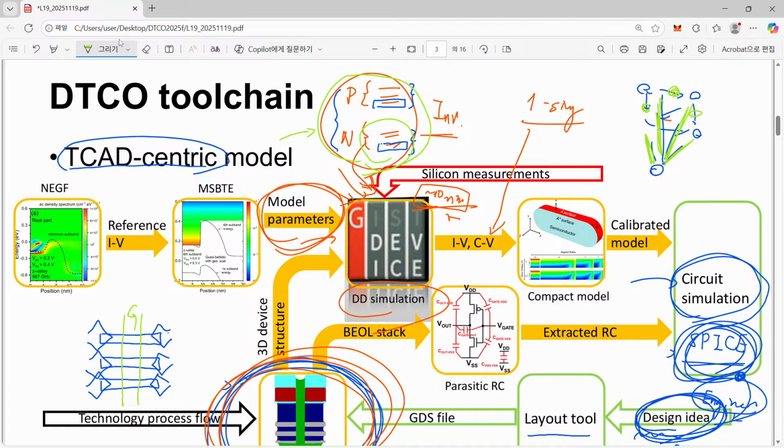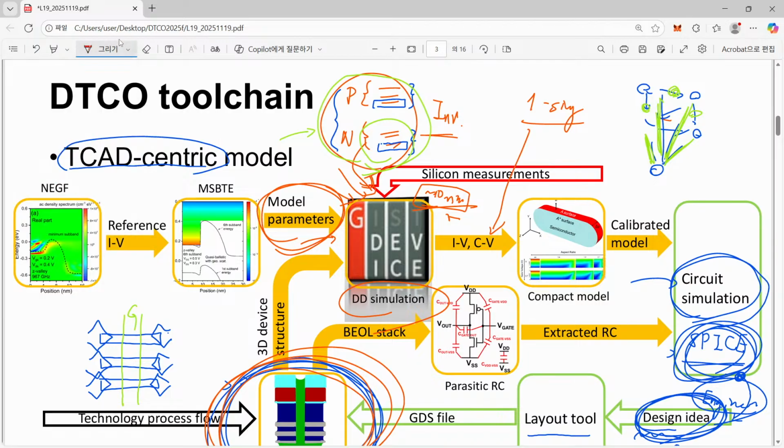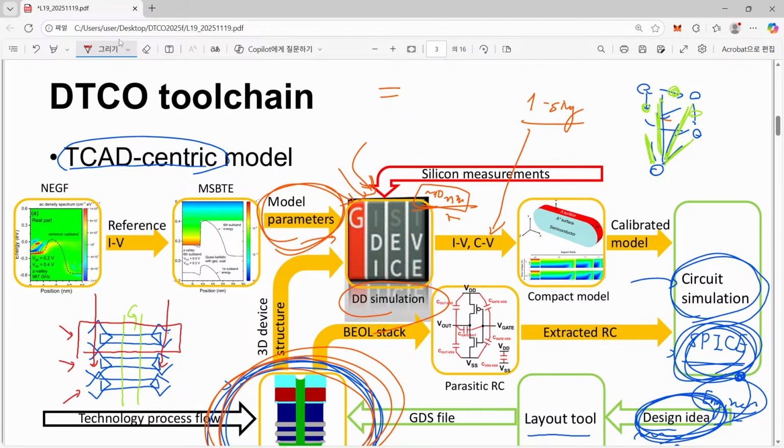If we have this situation, then previously we were allowed to consider only, for example, one single fin. It was because our metal comes from somewhere and is laid on top of it. So therefore, of course, depending on the position of each fin, this fin and another fin and another fin can interact, but their interaction can be relatively small. But now think about a different device called the nanosheet MOSFET.